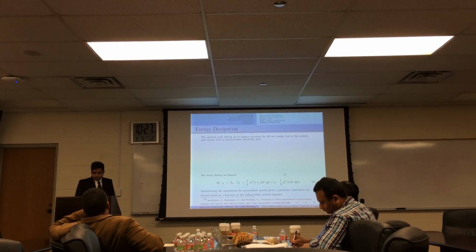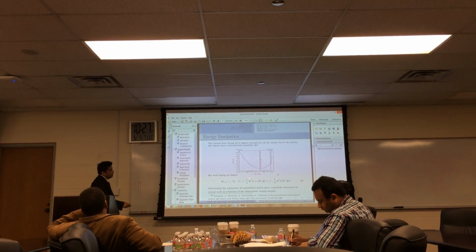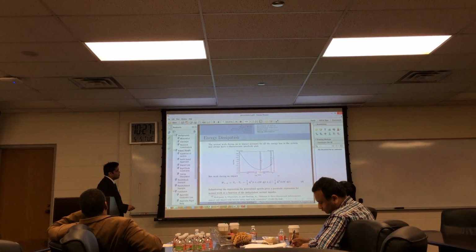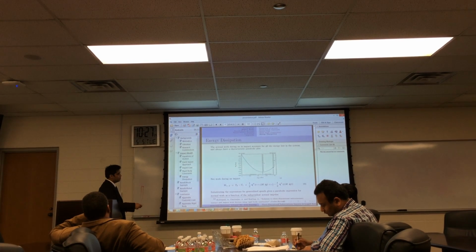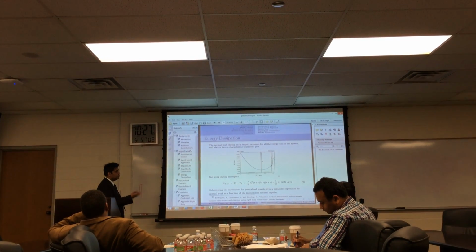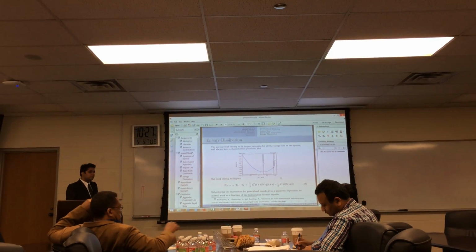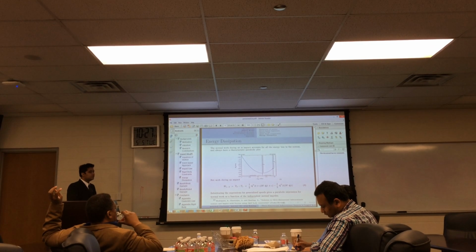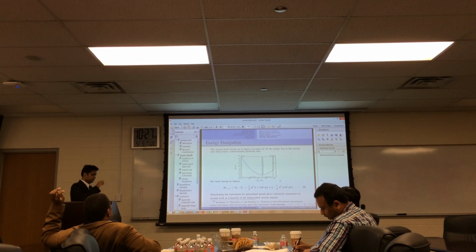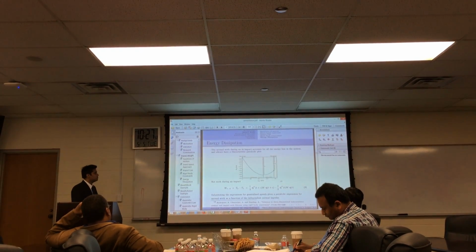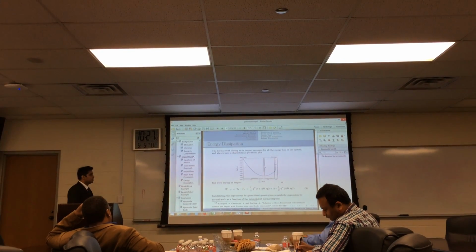And before that, in this parabolic equation, the part before the vertex is the compression phase, and the part after the vertex would be the restitution phase. In a deformable body, the compression phase would be the phase where the maximum deformation occurs, and the restitution phase would be when the body regains its full shape.